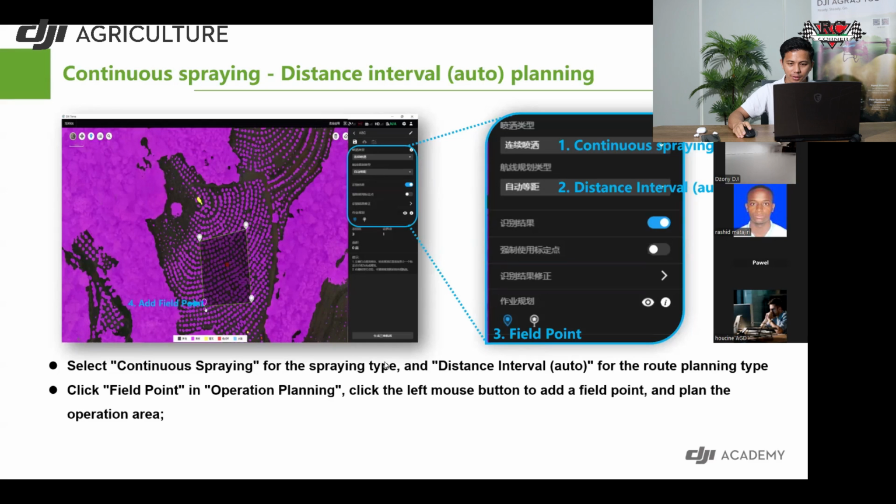This is a reference point for your field crops. For continuous, you may say, oh my friends, I didn't mark the visible points when I did the mapping. Before you do the mapping, you have to add the calibration point, like a visible point. You have to put it on the ground. This is a strategy to make the correction. As I already said, some of you may be from the survey industry, thinking about accuracies.